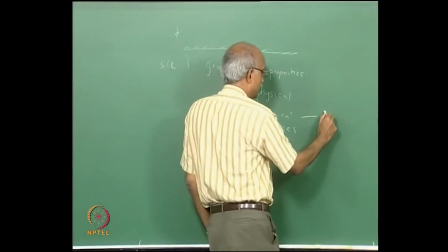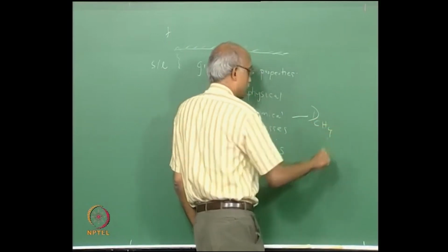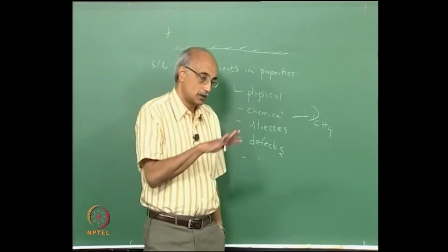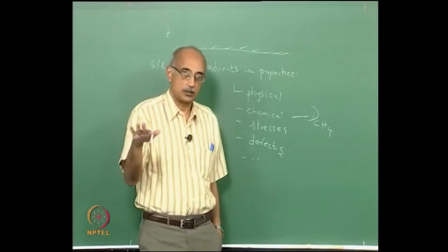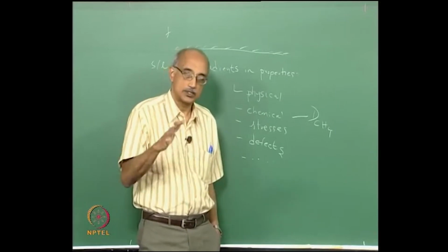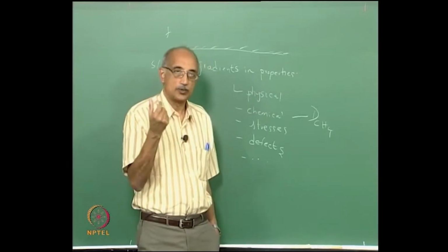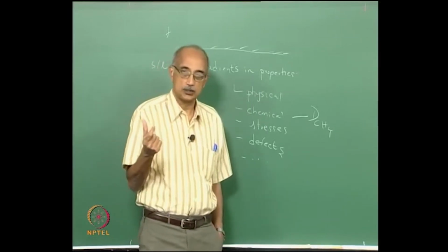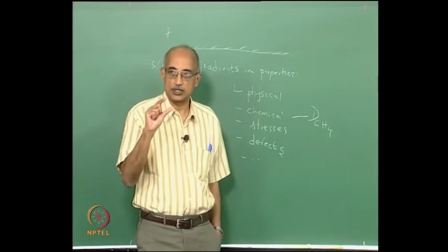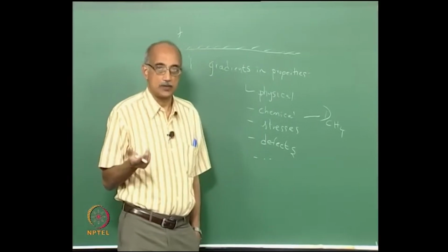species will diffuse with some diffusivity. So, let us say that you are using methane to achieve this carburization. This CH4 will essentially first encounter the surface of the alloy and it will leave behind carbon and therefore increase the carbon content. But then by controlling the amount of diffusion of this carbon containing species into the matrix of the material, you can control the depth to which this carburization happens, because the distance that this species will travel within a certain